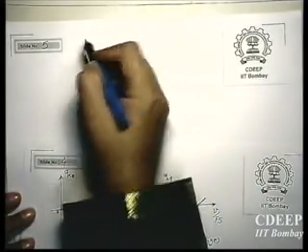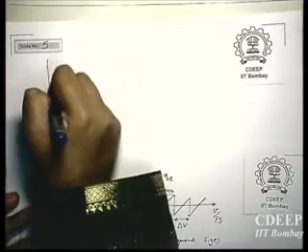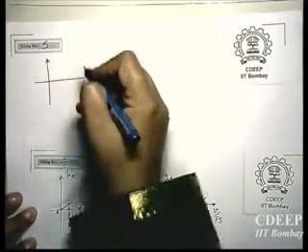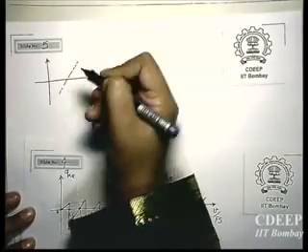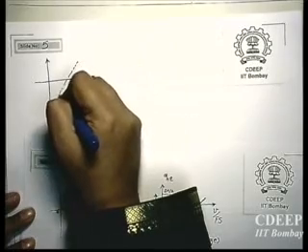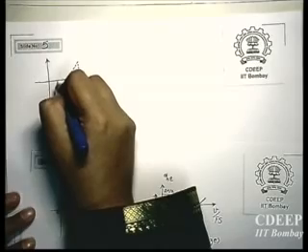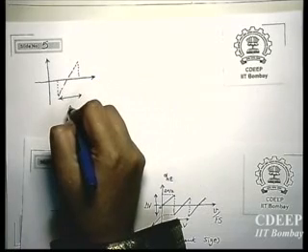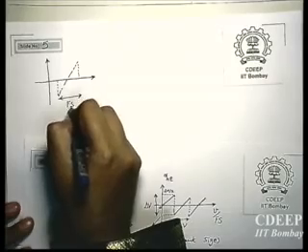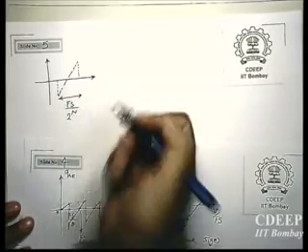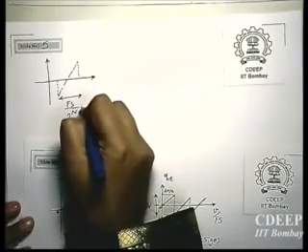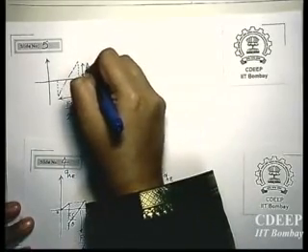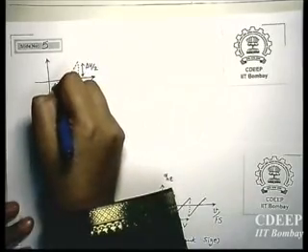So quantization error was like that, so we calculated. Quantization error is like that, right? Let me take just one segment. This was the segment size. For binary, for example, it was full scale divided by 2 to the power n, and eventually it was delta V. And this side was delta V by 2. This is also delta V by 2.